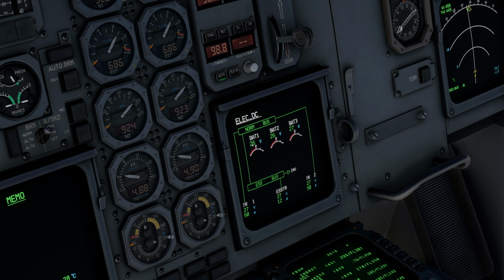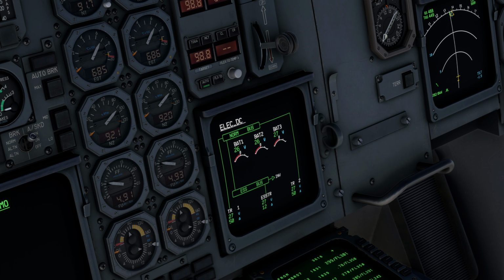the normal system checks, one of the 3 batteries has been showing amber. Typically the Airbus takes a little while to correct that automatically. However, it is good to notice these things early, and it is good to inform maintenance of these trends of the systems as well, which may not necessarily be transmitted automatically through the ACARS.